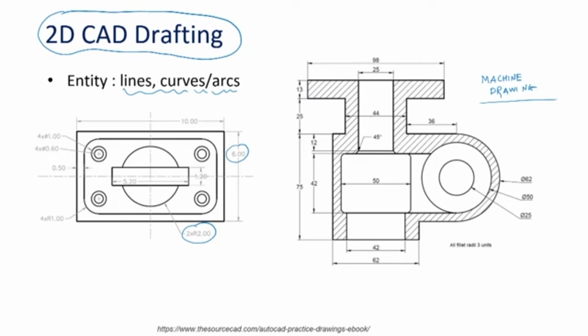Here you can see the hatch lines, and these hatch lines designate that some portion has been removed, and after removing the portion, this is the shape that we are getting. Wherever the hatch lines are not there, that portion is uncut portion, or it was void. There was nothing over here, that is why no hatch lines are given.